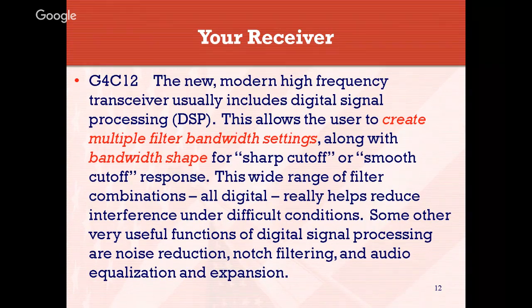Like if you're going to be on your HF radio, and you might get into contesting, and when contests are going on, the bands tend to get really, really crowded. And if you recall, your normal single sideband signal is about 2.8 kilohertz wide. And you may hear somebody maybe 2 kilohertz away from you.